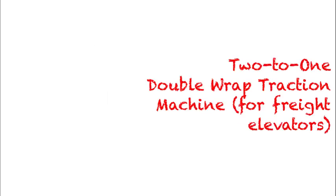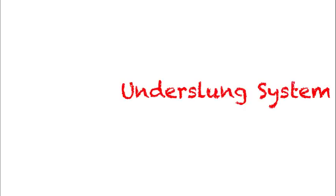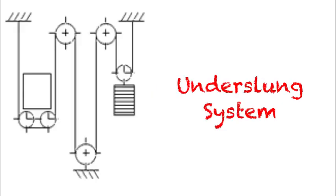2-to-1 double wrap traction machine for freight elevators. This 2:1 roping has a mechanical advantage of 2, which results in a high-speed, low-power, and therefore low-cost traction machine. Underslung system is used where the elevator machine is located at the basement.